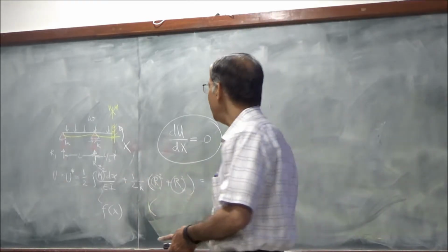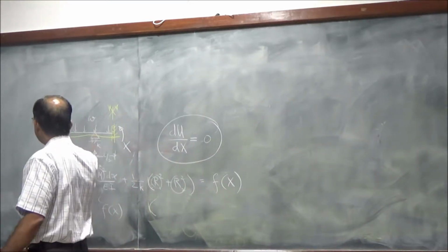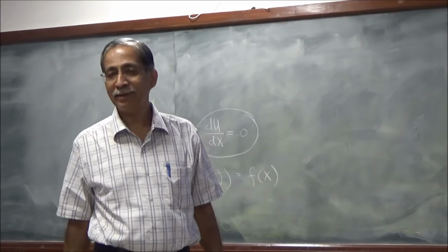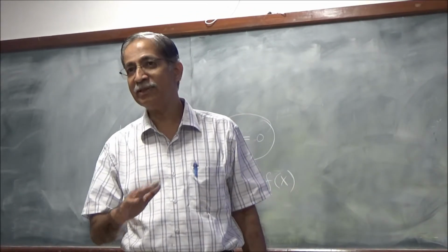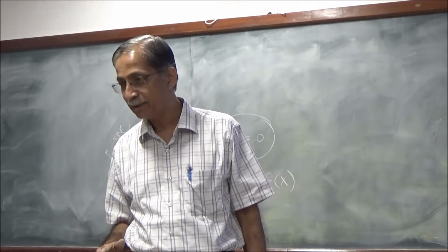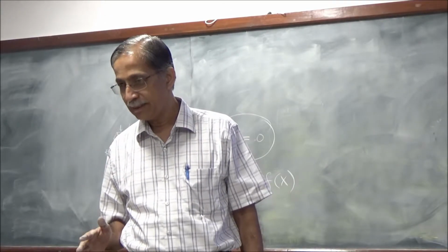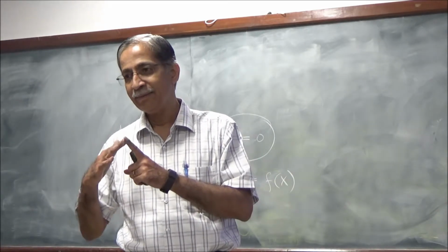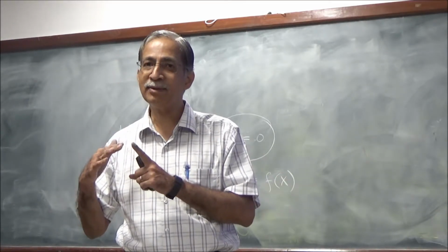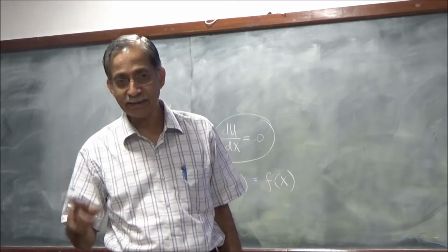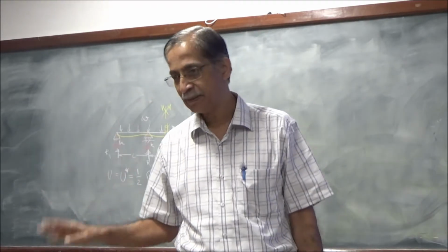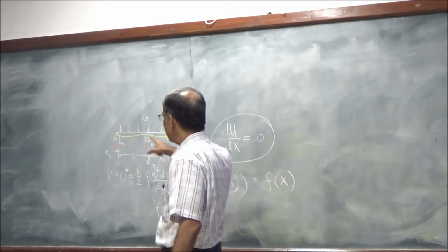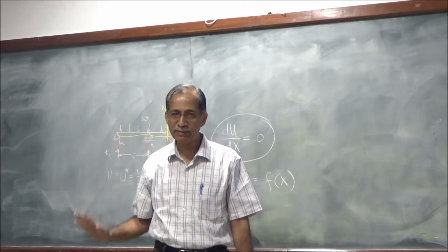The other assumption you're making is that the beam and the slab actually give some torsional restraint, right? Which you're ignoring. Do you know that? It's an L beam, no? So you've got a partial rotational restraint, but there's a reason why we're ignoring. We'll see that later. Is it clear? But no harm in doing this and knowing that you're making an assumption and going ahead with it.